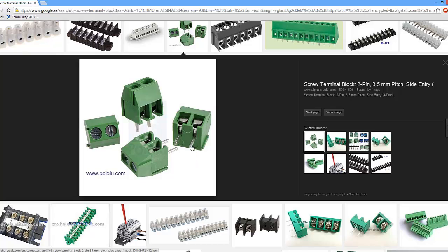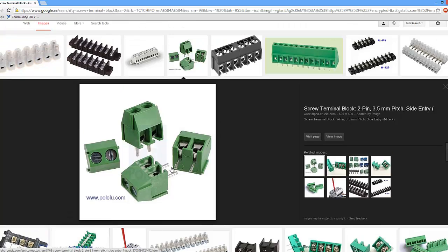As you can see, you can solder it no problem from the bottom, but once you solder it on the bottom, there is no way for your soldering iron to reach and for you to place solder on that place on the top side. You get my drift? You cannot get your solder iron in there, place solder, and connect to the copper at the same time. It just won't happen. Either you have some new tricks that I don't know about, or you don't care. You would destroy the whole plastic just to solder it from the top side. It's a big hassle, and seriously, you don't need to go through that.